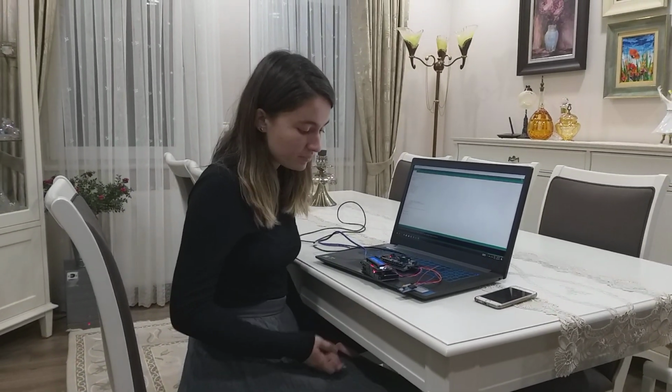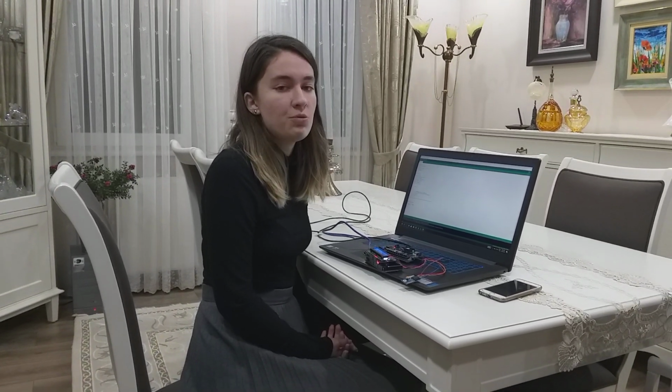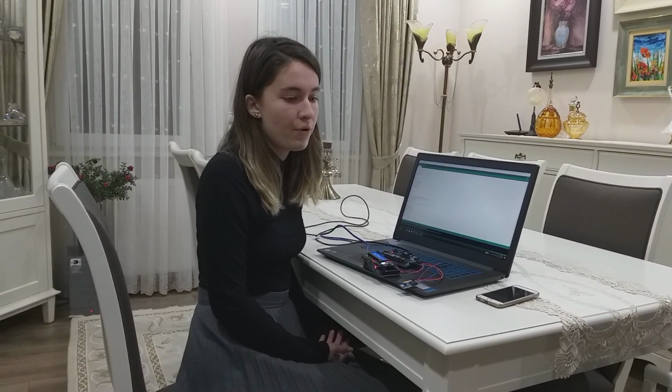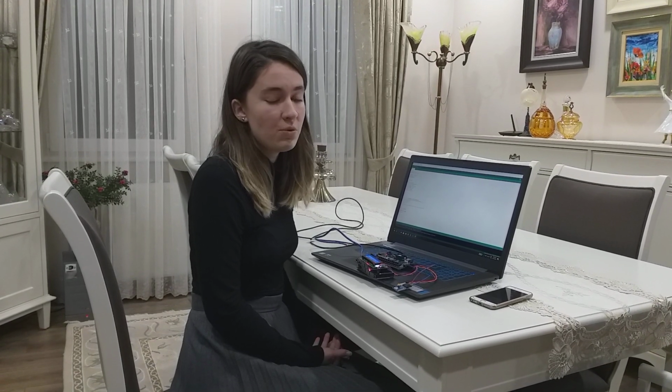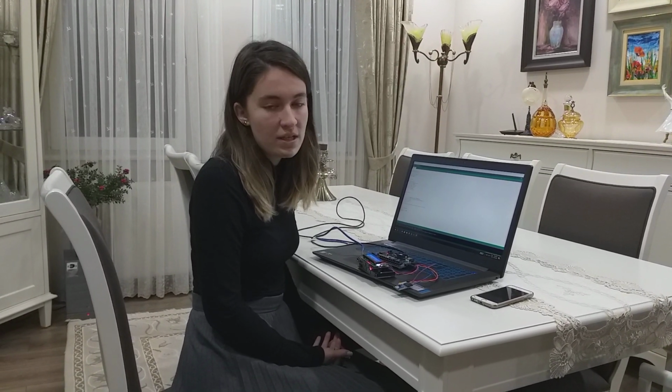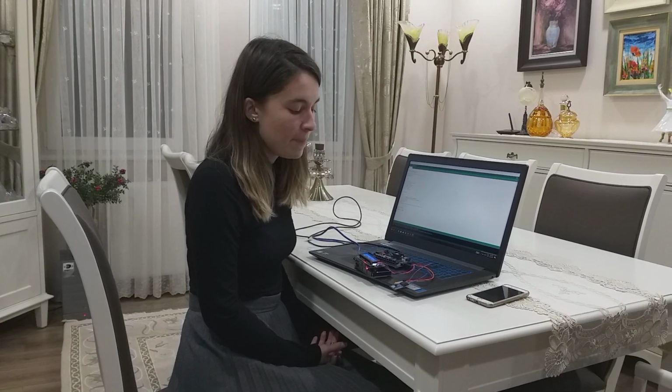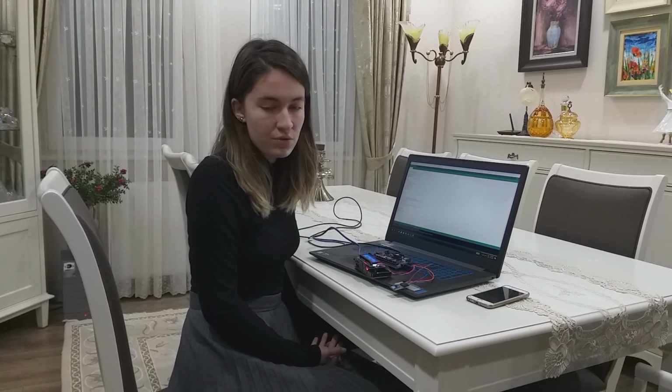It creates this communication by using only 4 ports. Two of these ports are for data transmission. They are the data transmission lines. One of them is MISO, referring to master in slave out, and the other one is MOSI, the master out slave in. And it has 2 other ports. One of the ports is SS, which is the slave select port.